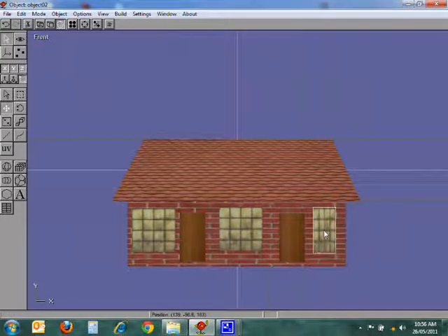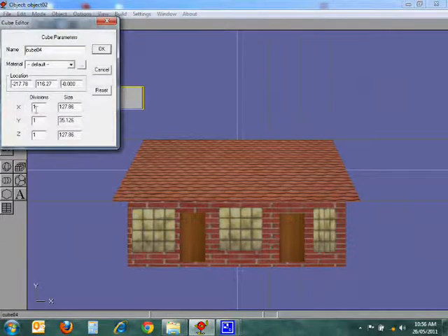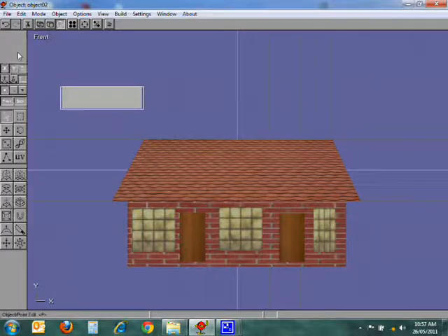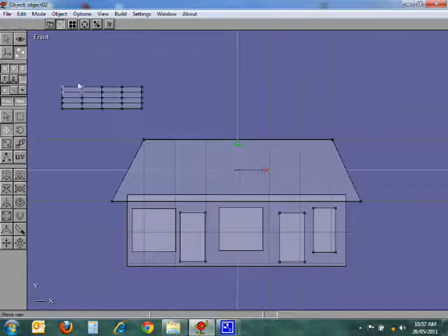So to be able to modify things, remember you have to select the object and you should convert it to a mesh. What if there are not just 4 dots? You wanted more dots. See that? That's a rectangle. Double click that. How many dots you wanted on X? You can go, I want 4 dots. I want 4 dots on Y. So at that time you can say build, convert to mesh. If you're looking at the dots now, see those many dots you have. So you can go and modify them in whatever the way you wanted and then create whatever you wanted out of that.